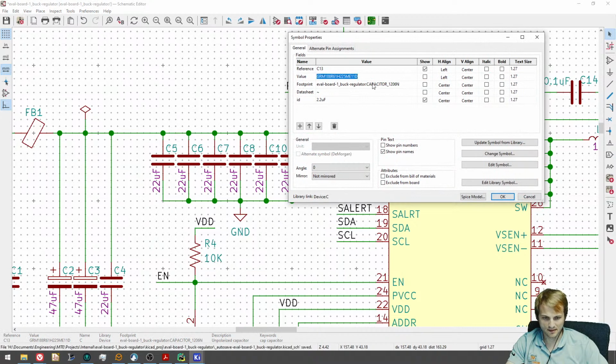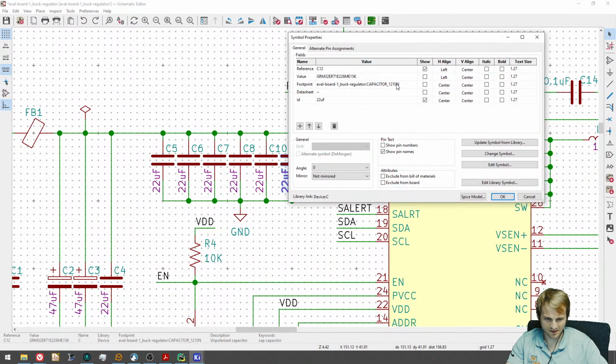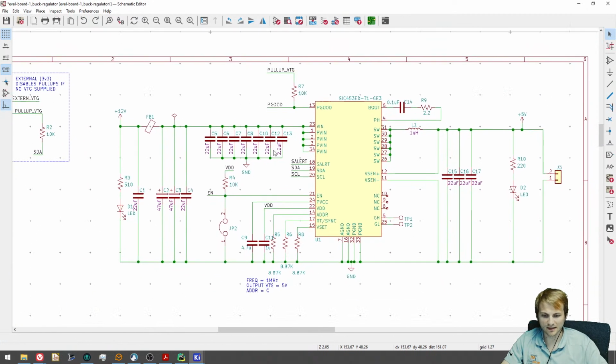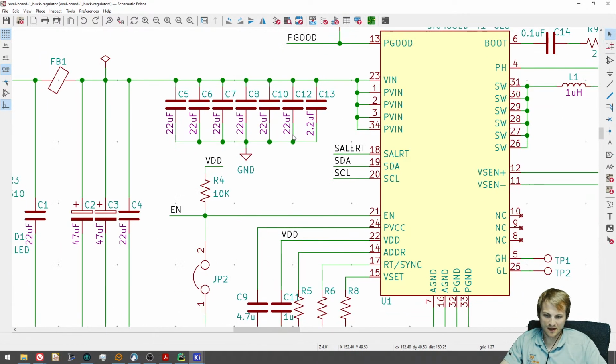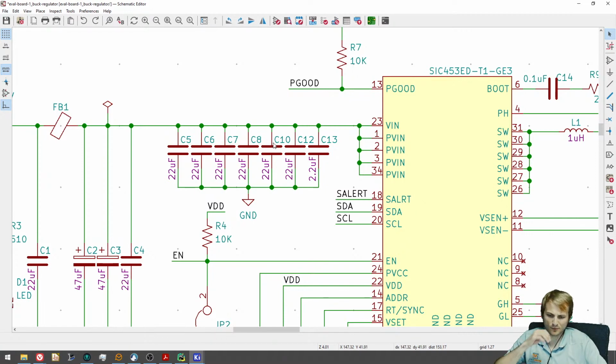that's not right. That should be 0603. I know that because I literally finished changing these like 2 minutes before the, oh no, sorry, it is 1206. I was thinking 1210. I finished this like the second that the stream was about to start. So this is a 1206, a little better for high frequency noise than the 1210, and they're close enough in value, or at least this is a high enough value, where we shouldn't get that anti-resonance peak with different valued caps in parallel like I've mentioned before.